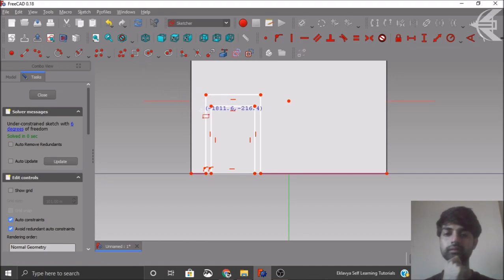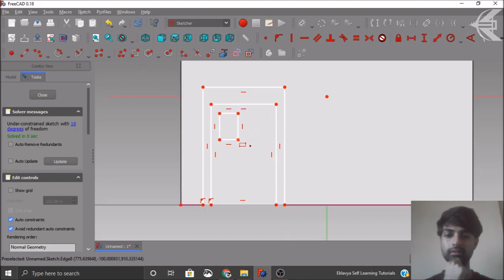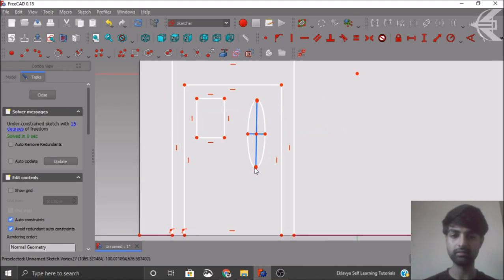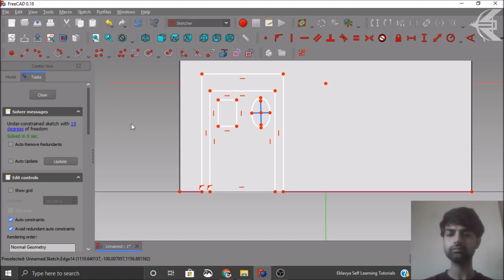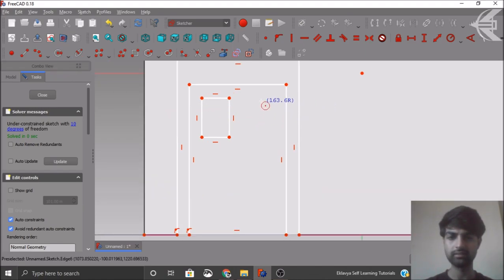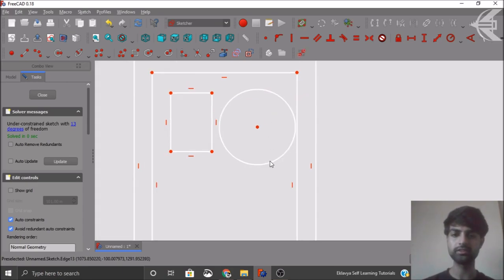Let's create one here, and let's create in the shape of an ellipse. So this is an ellipse that we have here. Let's make it a little bit small, and let's place our ellipse here. Okay, let's create a circle actually. This will not do much. Let's create a circle by center. So yeah, we'll change its dimension later on.